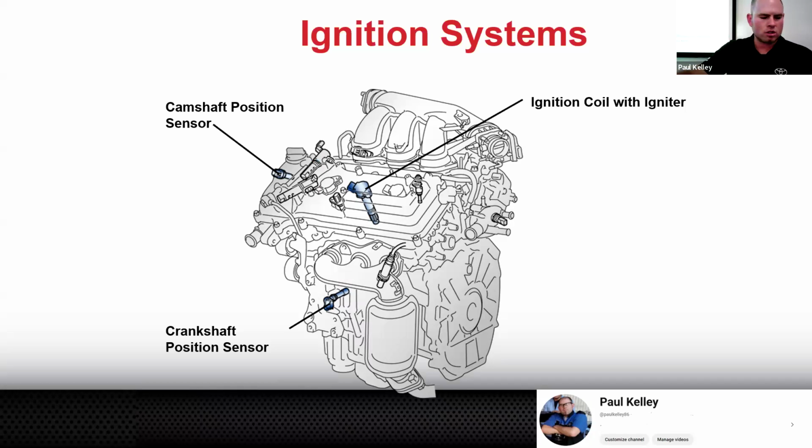And she's kind of like, the smaller wires? And I said, yeah. So she sends a picture of the small wires going to the coil, all sorts of jacked up. And I'm sort of like, stop right there. You need to fix that. Forget about the spark plug. Forget about all that type of stuff. You need to fix those small primary wires going to the coil. And then probably that's going to fix the whole thing. But if it doesn't, I'll give you your next steps, right?